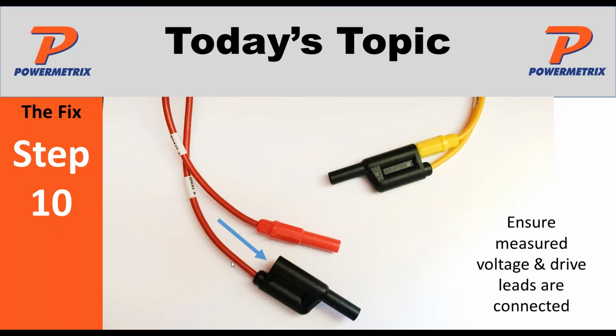Now, of all the steps that I've mentioned here, the first step I would do, I guess, is inspect my test switches, because I have seen a lot where the test switches are full of corrosion and all that good stuff. So you may want to clean those and then start the steps that I've gone over here in the training. But that's exactly what I would do.